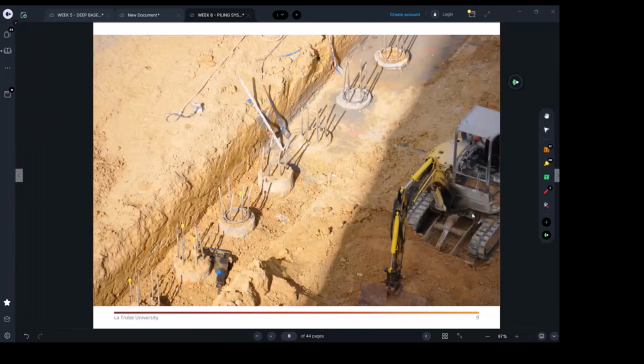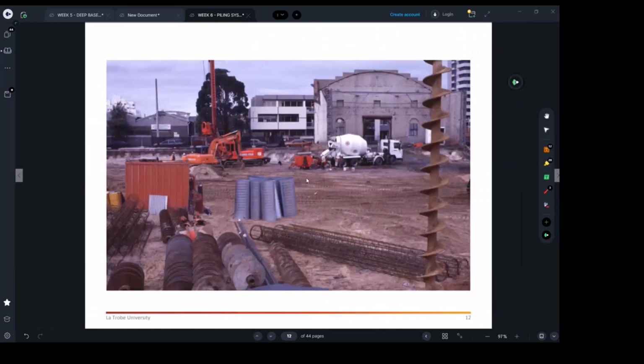So we use these kind of barrels. After we make, say, a 900 diameter opening in the ground by using the drilling buckets, then we're going to place this. Then that's it. We're going to use the augers. This is just the front part of the auger to go through it and start digging. We use this when we have very deep piles and the soil is not self-supporting, which is mostly what we're talking about in our examples.